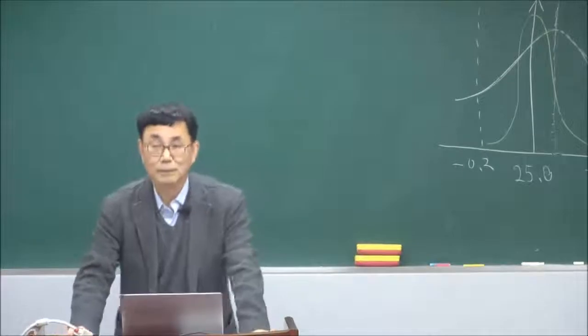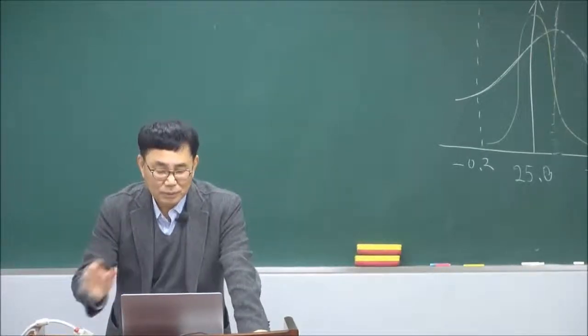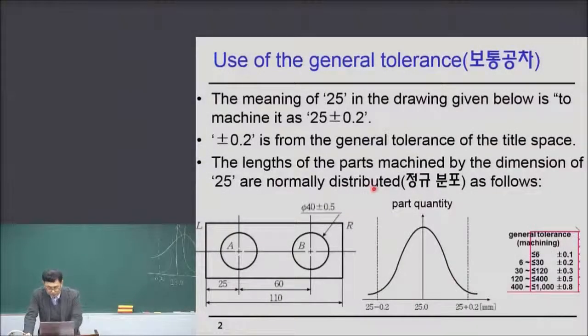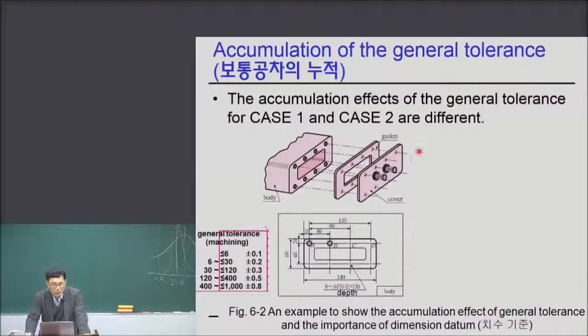Okay, all right. Let's go to the slide mode. So anyway, the general tolerance is very important. The general tolerance must be included in the title space of your drawing. And another aspect is that the general tolerance is accumulated. It is a very important concept.